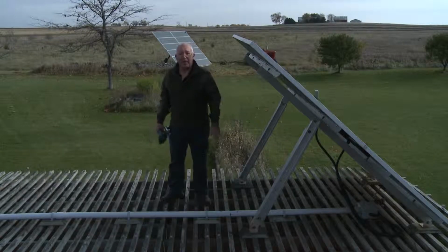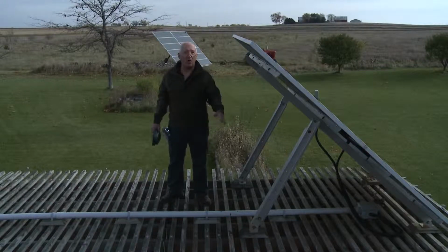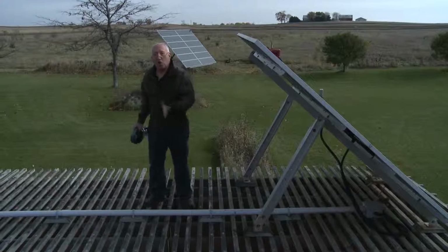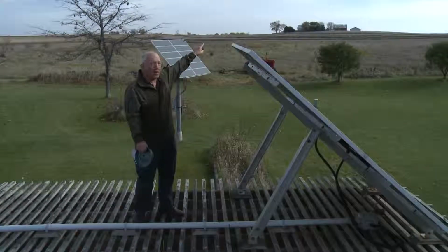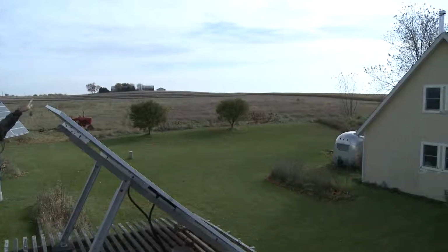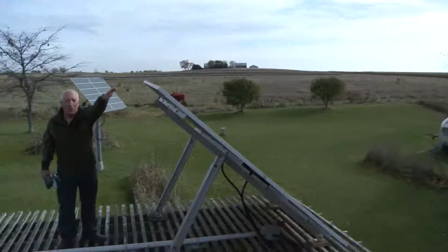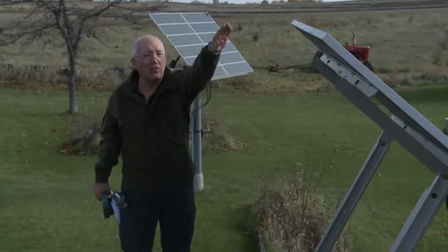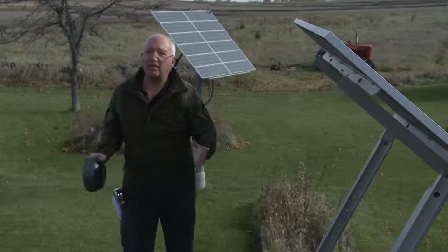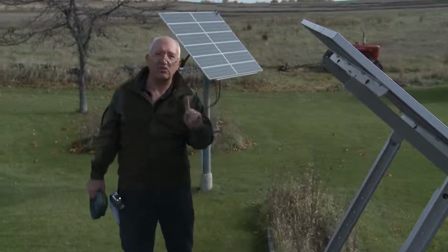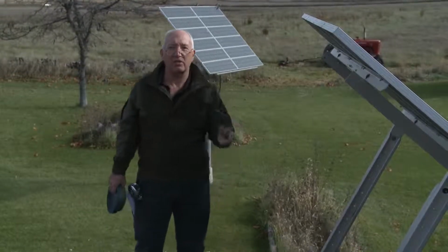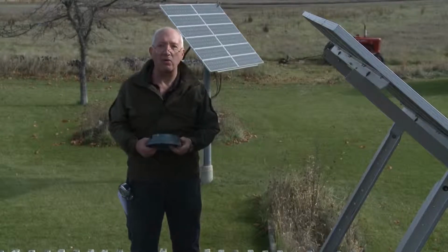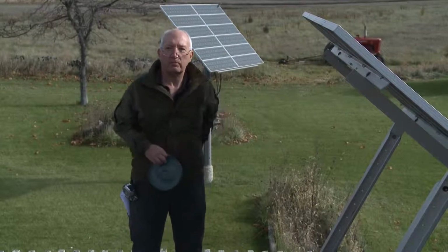The problem with that is that the shadow within our solar window between 9 a.m. and 3 p.m. gets longer than that, because at 9 a.m. when the sun comes up, the sun is lower. At 3 p.m. late in the winter when the sun's getting ready to go down, the shadow is longer because the sun is lower. We actually need to space longer. So instead of being a single trig calculation, this becomes 2 trigonometry calculations. So let's go through how you would approach this.